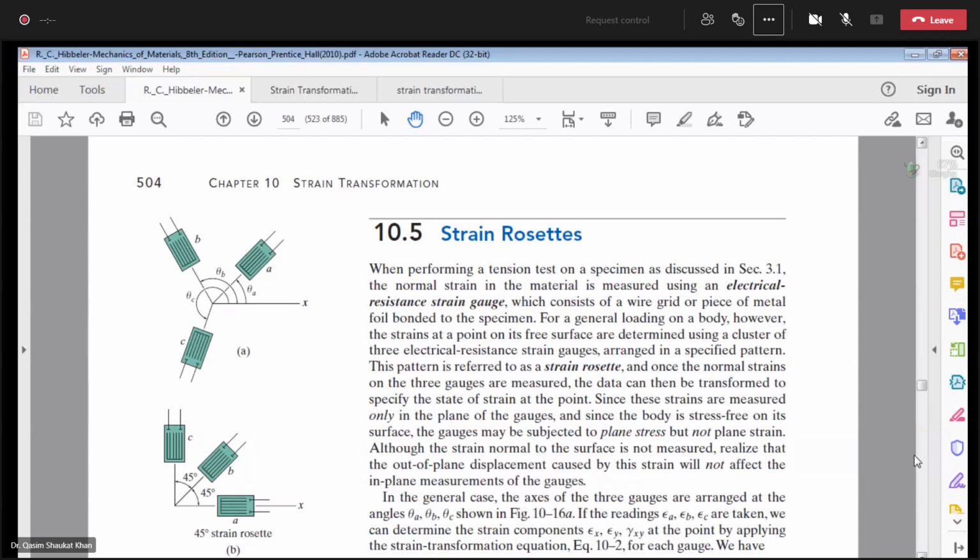They cannot measure the strain in the perpendicular direction to the strain gauge direction, or shear strain. Now what we are going to do, we have the data, normal strains from the strain gauges. With that strain data, we want to calculate the shear strains, the normal stresses and shear stresses. So we are going to derive some material property relationships. And we will also focus on how we can get the shear strain value from the normal strains, because we are just measuring normal strains, we are not measuring shear strains or the stresses. So how can we get that?